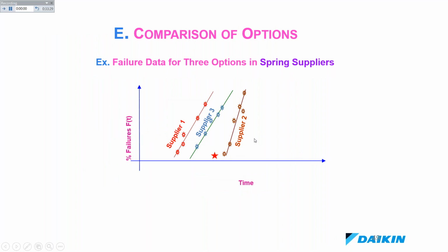I put those different suppliers' values into a Weibull plot, and here's my target, and I know the winner right away. So I would be working with this supplier, not the other supplier. Now this is valid not only for suppliers, but for different design options and different materials. We could qualify very decisively. We can decide on those options, and these are things that we come across every time.